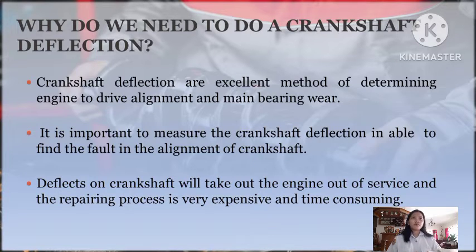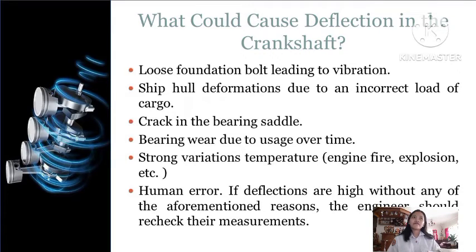So what could cause deflection in this crankshaft? In these slides it talks about the possible causes of how or why a deflection in a crankshaft could occur. First, it may be a loose foundation bolt leading to vibration.